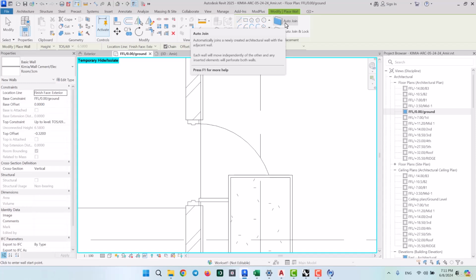You see, when you draw the hard walls and the finished walls all the same, as in if you try to draw one multi-layer wall, then you'd have to adjust their heights one by one, rectify the grooves. You also won't have a separate schedule, like you can't get a schedule of only the finished walls, and it's just going to make things a lot harder, so it would be a lot easier for you if you draw them separately, especially with this new tool that's been added to Revit, this Auto Join. Now we don't have a reason not to draw the walls separately.